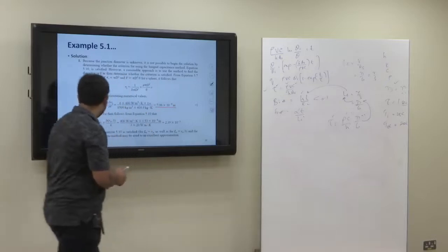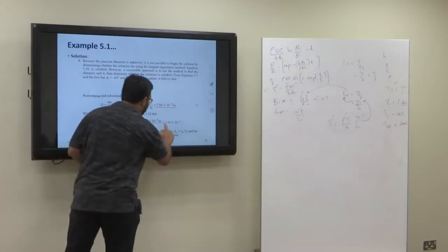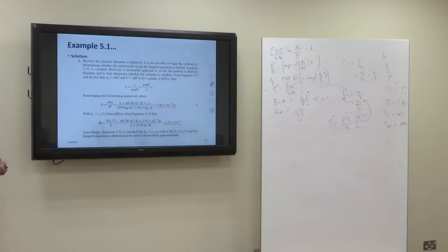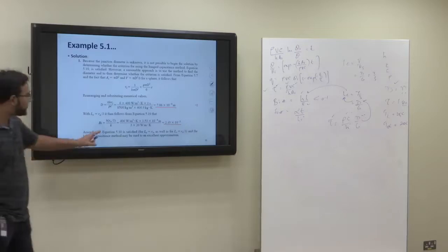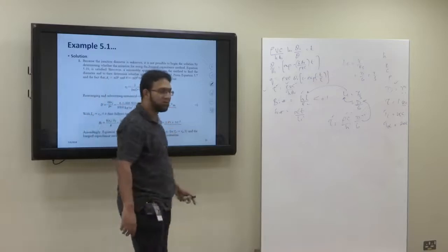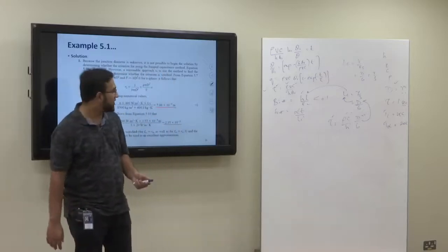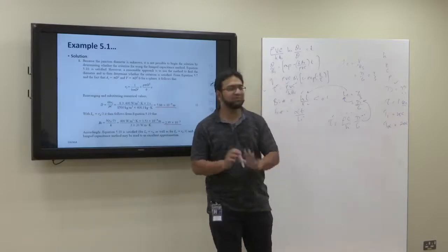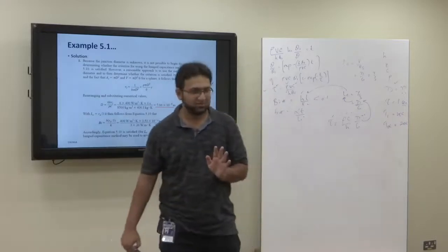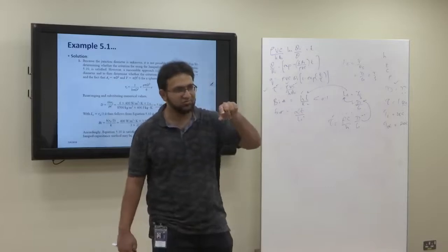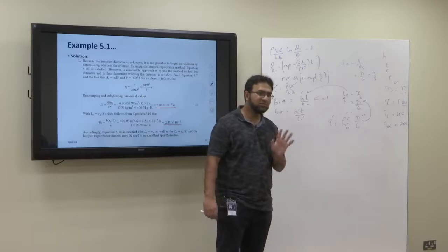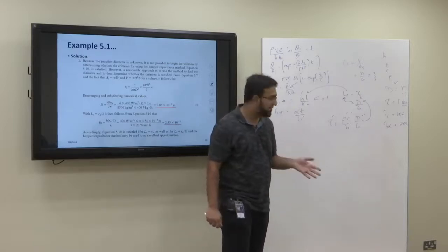After finding the Biot number, it comes out to be 2.35 × 10^-3. What do you think? Do you think this value is greater than 0.1 or less than 0.1? It's less than 0.1. So if it is less than 0.1, that means it's applicable. That means our diameter is correct. So we went the other way around to solve the problem. So that was the first part.